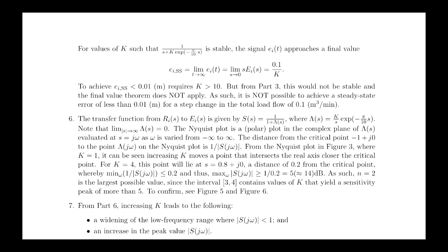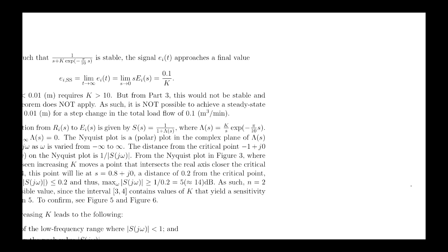We saw a relationship, right? In fact, one measure of how close your Nyquist plot is, the measure corresponding to drawing little circles around here until you hit the Nyquist plot, is telling you about the peak gain, right, in the sensitivity function, right, because the little vector from -1 to the Nyquist plot is 1 plus lambda. Right, so 1 divided by the smallest this can be will give you the peak gain in the sensitivity function, which is 1 on 1 plus lambda.